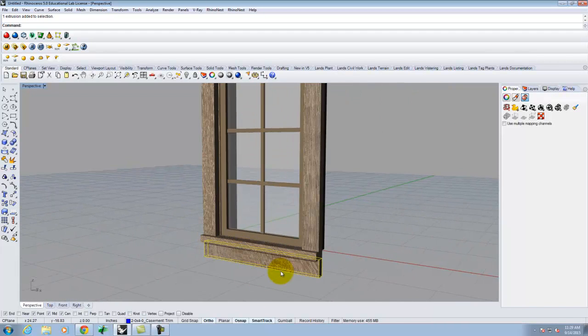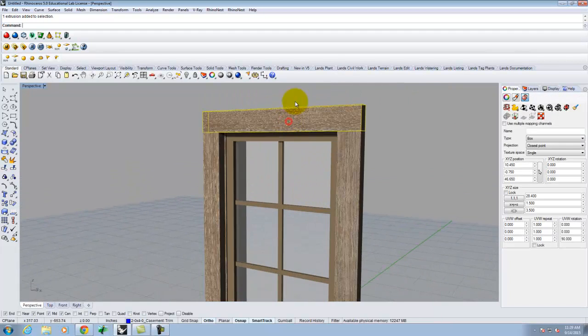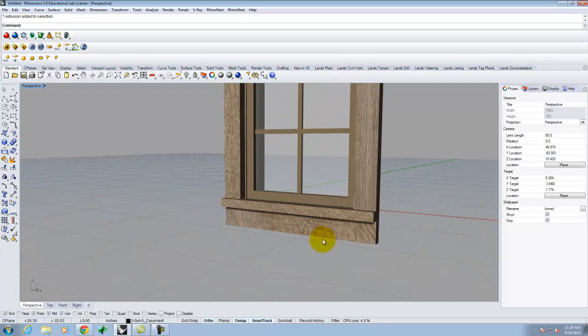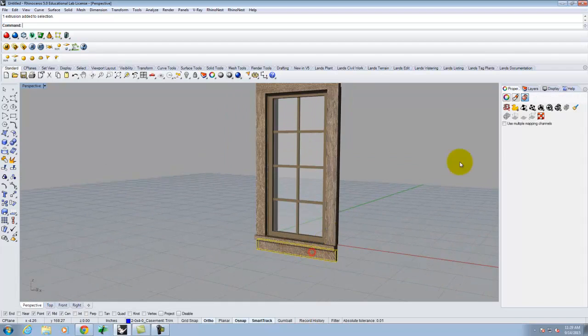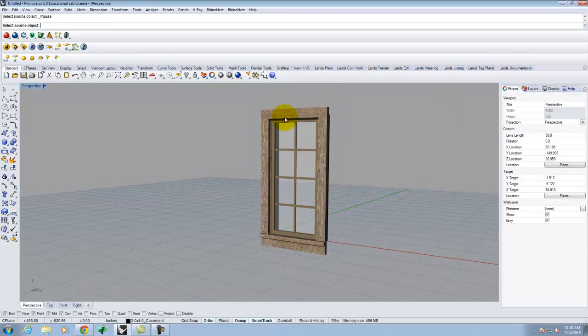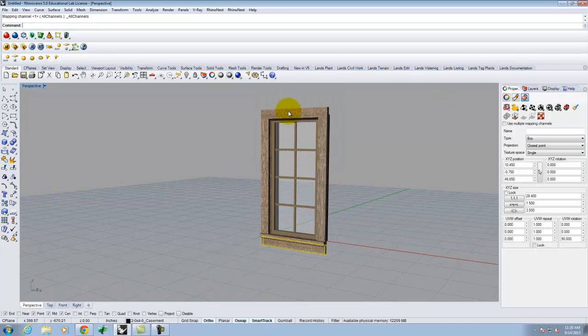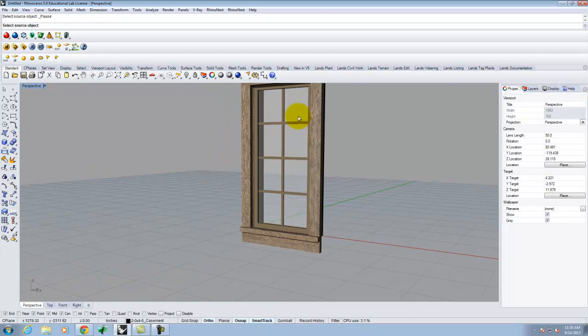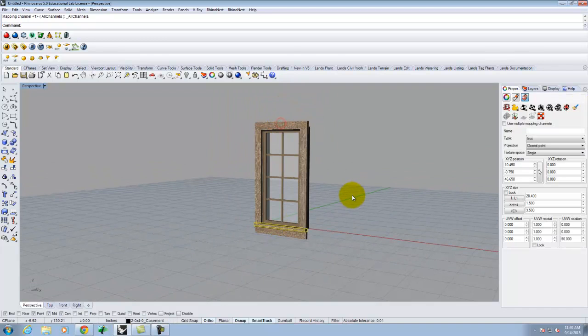Now, in this instance, I already have the texture mapping set correctly here. So instead of retexture mapping down here, I'm going to select this object, and go to this little broom looking thing that says match mapping. When I click on that, it's going to say select source object. I'll select this upper one, and I'll just copy the mapping since I already have it set right. So there, and we'll copy it there as well.